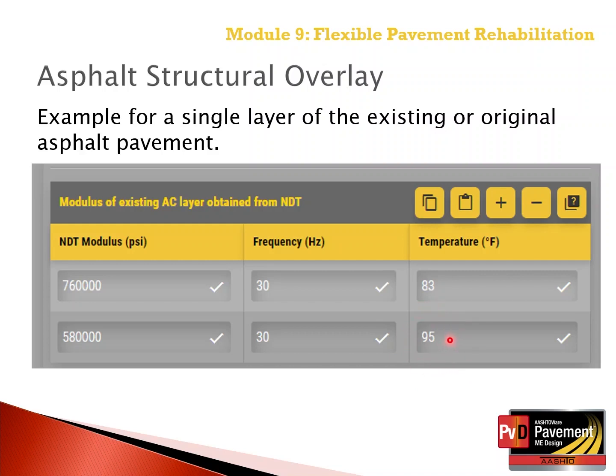The temperature at the mid-depth of the existing asphalt layer will be higher, and so the back-calculated layer moduli should be lower. So this is simply a screenshot of the back-calculated asphalt layer modulus values when the existing asphalt pavement is simulated as one single layer, but the deflection testing was grouped into two different temperatures. Not necessarily design segments, but within the same design segment, just different temperatures.